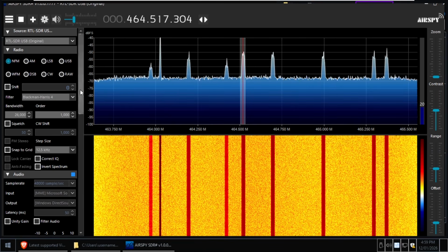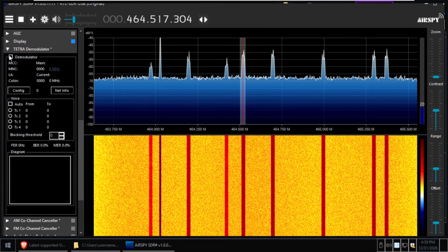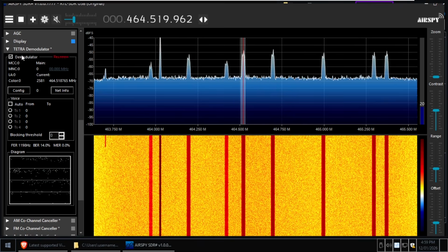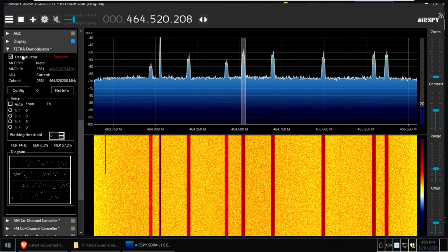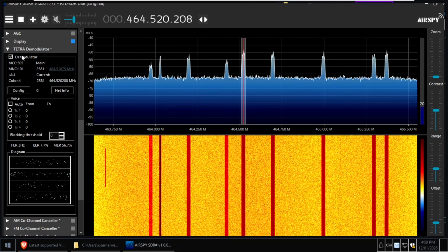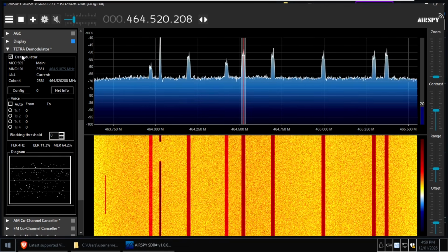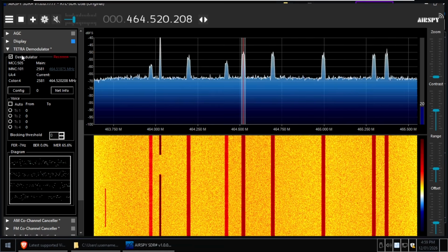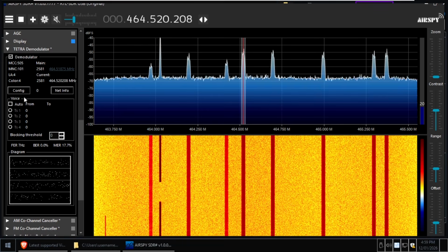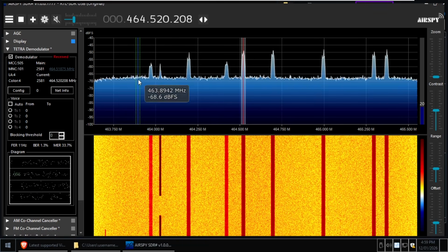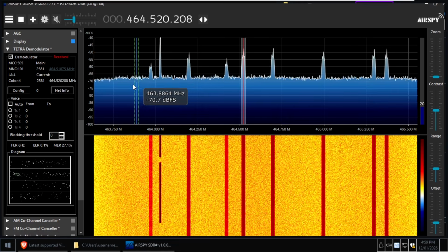So that's cool. Let's scroll down here and tick this demodulator button in the plugin. You'll hear the audio go silent, right? That means the plugin's taking control. It's taking the raw audio from the signal, doing all the demodulation and decoding in the background, and all we're going to hear through our computer speakers now is pure Tetra voice. I don't know if there's going to be anybody talking on this particular channel, but while I'm explaining stuff, we could probably have a look.